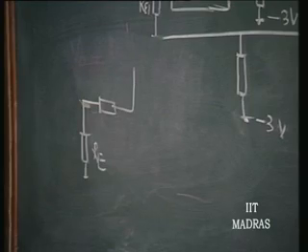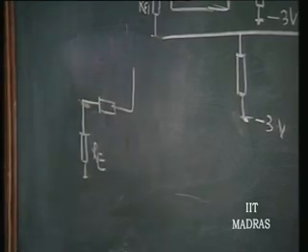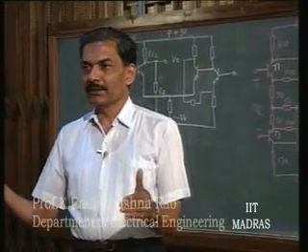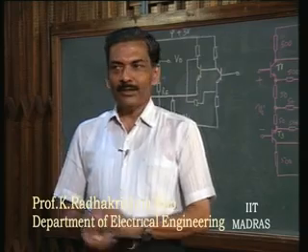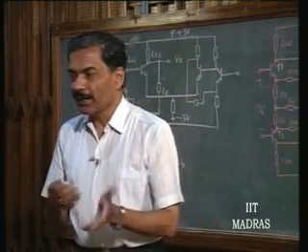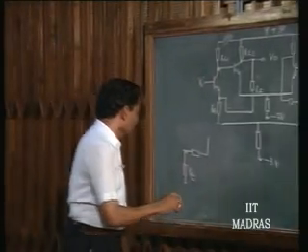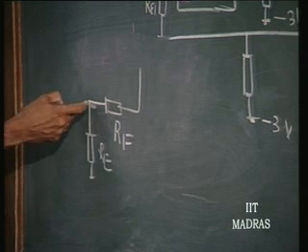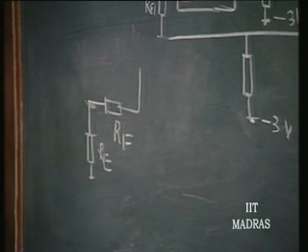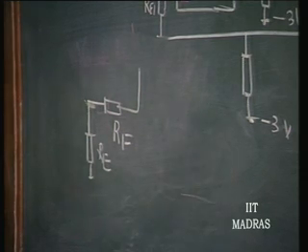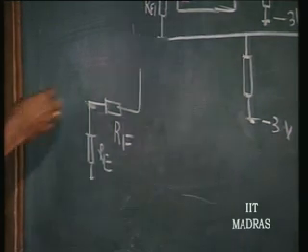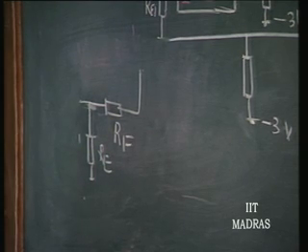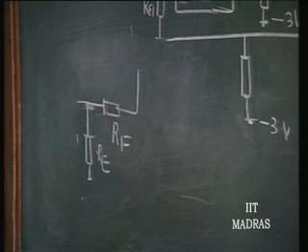The dominant pole compensation is called lag compensation. Okay. What will you call the zero compensation? Lead compensation. Okay. So, pole zero compensation is obviously lead lag compensation, which is the other terminology used. So, how do you therefore introduce the capacitor? Lag compensation is going to result in, if you put a capacitor across RE, there will be a lag between the feedback voltage and the output voltage. If you want this to lead slightly, what will you do? You will introduce a capacitor across RF.